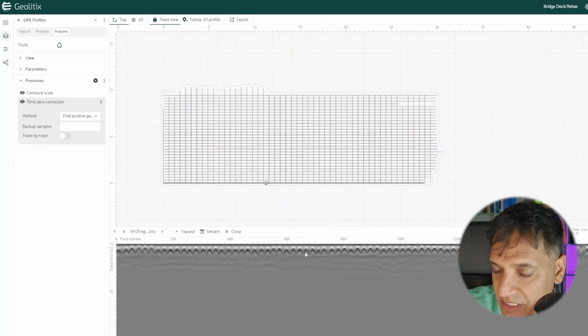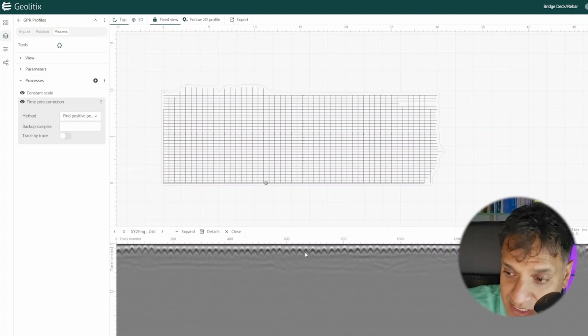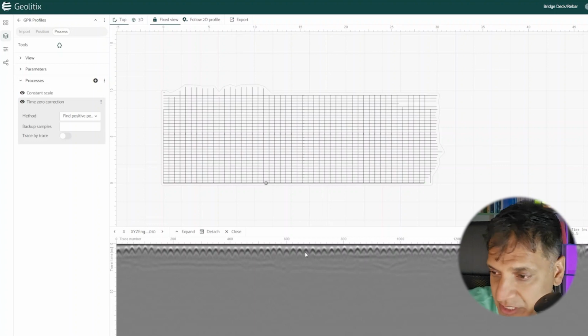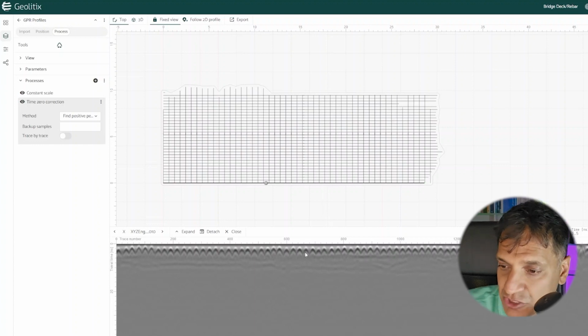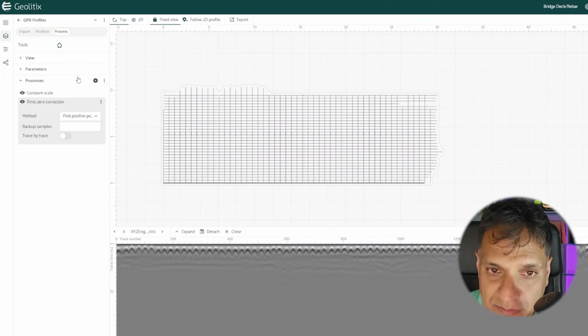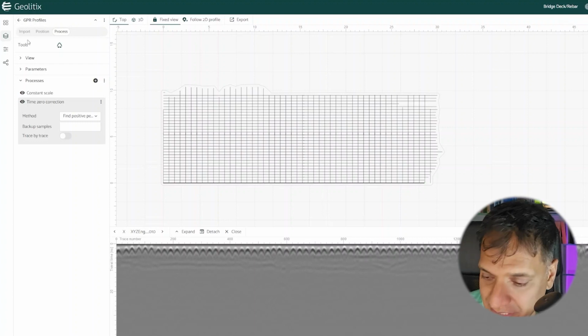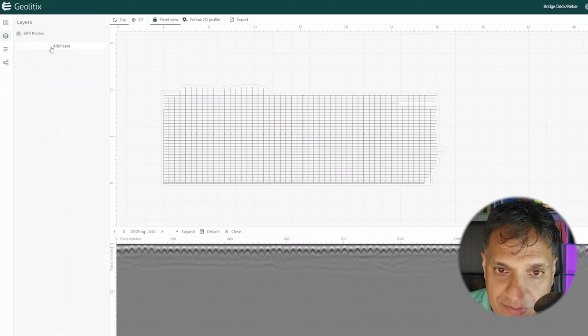In fact, it's not linear. Just because you have a lower amplitude doesn't mean you have corrosion. There are many other reasons that could create that, including surface coupling issues, increased moisture, or just a deeper rebar. But in this case, let's just use that analogy and use that assumption that we're trying to map depth of cover and amplitude. All right, how are we going to do that? Well, we have to pick each hyperbola, ideally. Okay, so, well, let's do that.